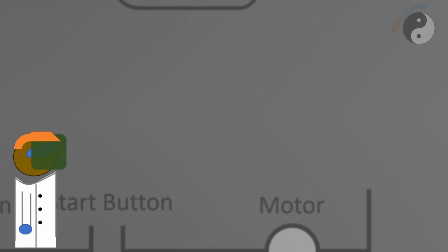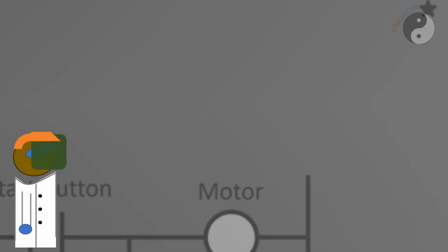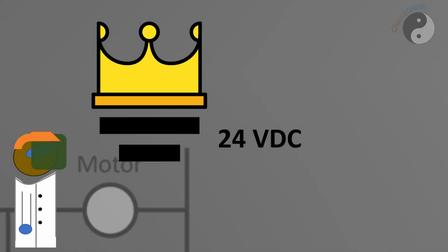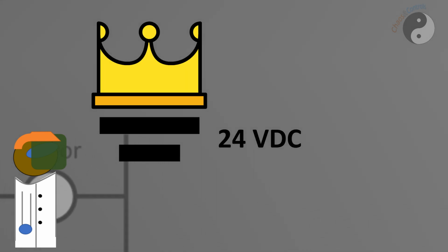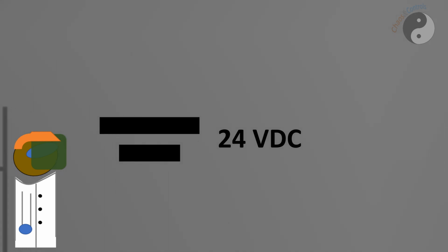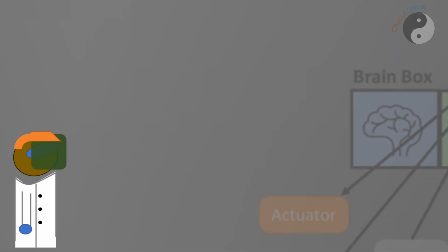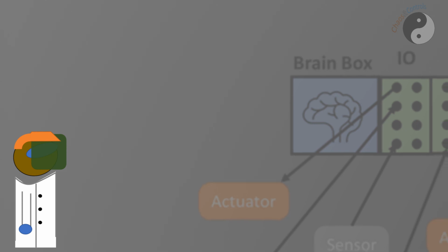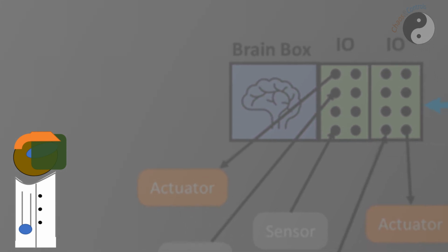Now, in industrial automation, you're going to find that most things really like to use 24 volts for whatever reason. And even still, a lot of your sensors and your inputs, you're going to have the option for a discrete input that either sees 0 volts or 24 volts to get you your 0 or 1, on or off, yes or no kind of answers. But you could also have a 0 or 120 volts.